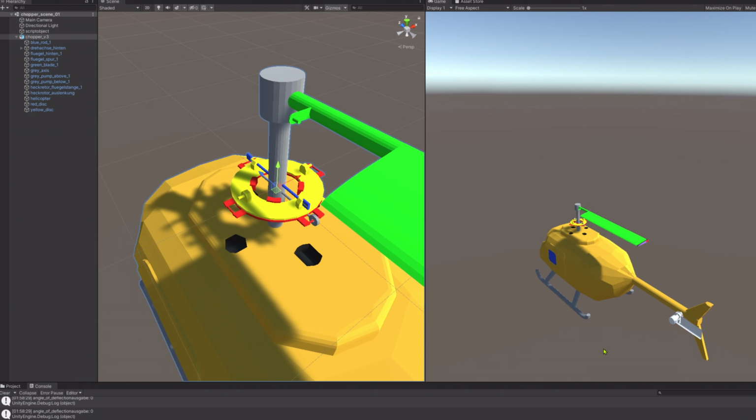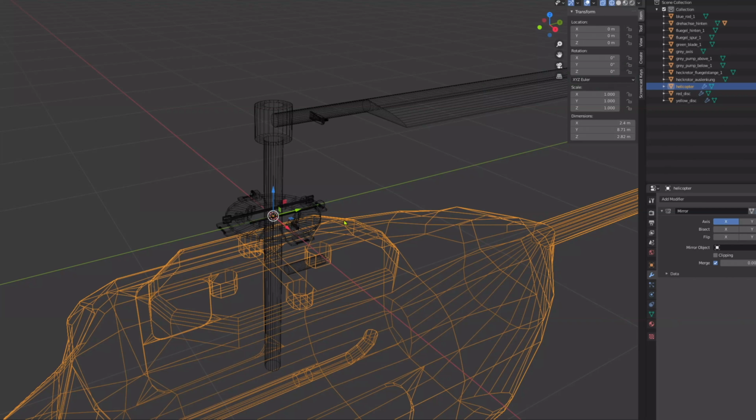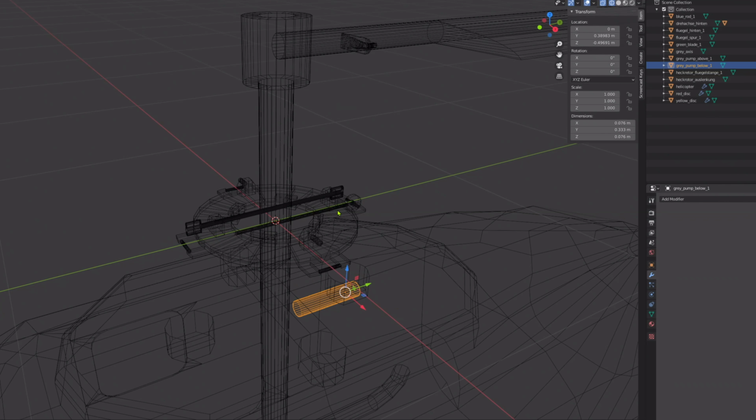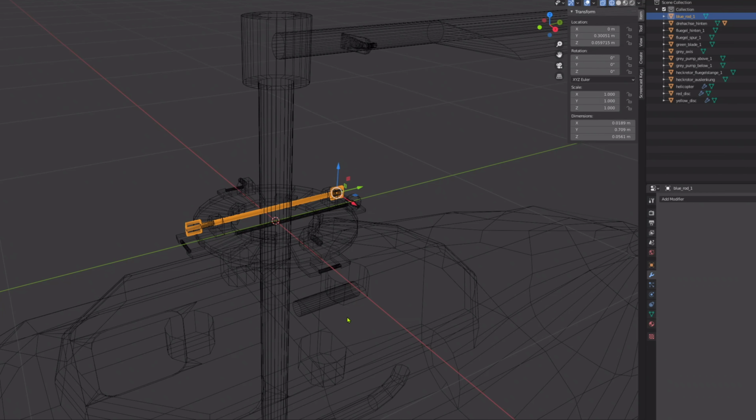If I want to use a look_at function in Unity, I have to orient my game objects in Blender accordingly, and I also have to consider how I'm going to export the axis, like I mentioned before. Here I have to make sure that the negative green arrow of the Blender system will be the direction I'm looking at